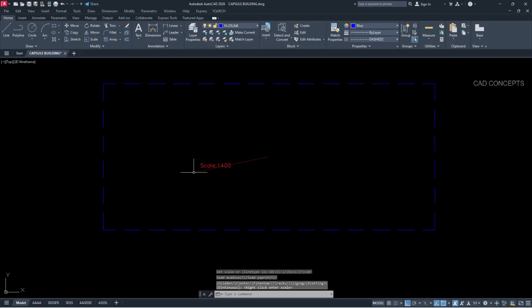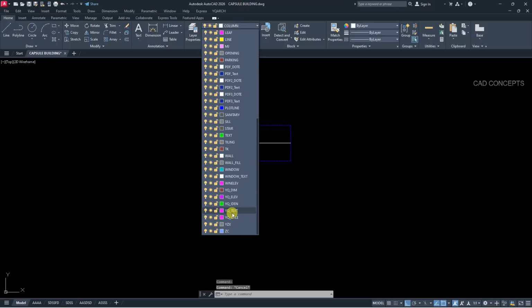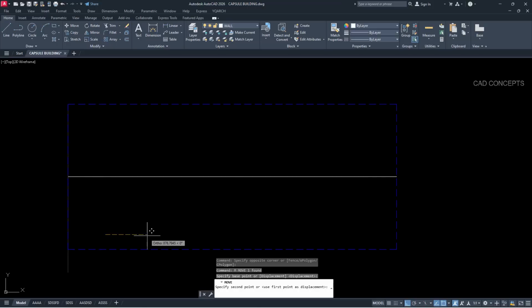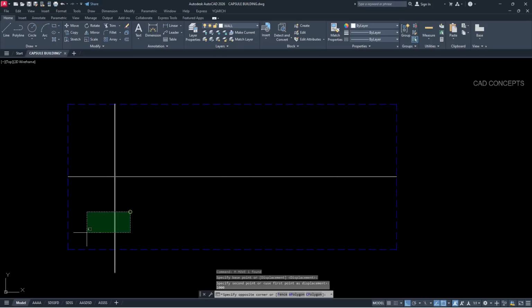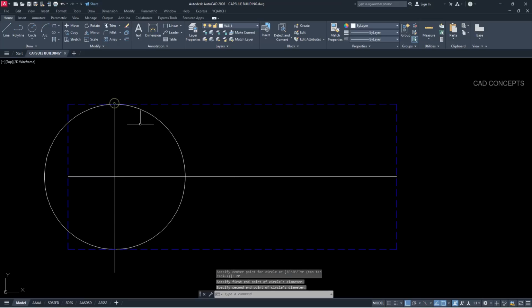See, let's do this very carefully. If you miss one thing, you miss a lot of things, okay. I have scaled this line type, okay. Now let's go center to center from here. So this is the wall layer we have here, okay. And let's draw a straight line and move here, okay. 1000 centimeter and a 2-point circle, first point, second point, okay.